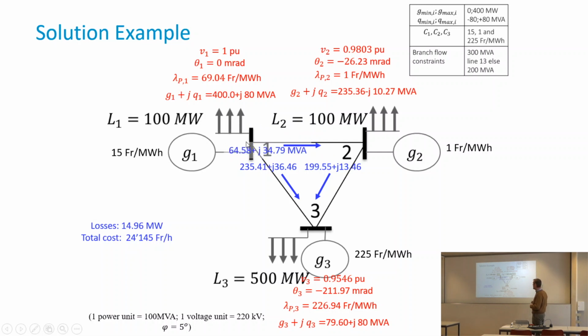So even if you had a generator that produced purely active power, which means the current and the voltage are perfectly in phase, there is no reactive power. Even if that would happen, at the other end of the line, that would no longer be the case. So the lines cause reactive power. Because they cause reactive power, they increase the losses. One way to reduce that is to compensate by injecting, or here consuming, reactive power into the system.